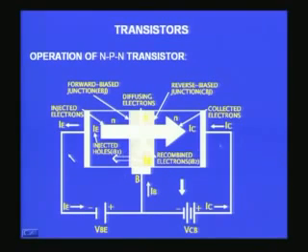So in the basic configuration, we can say there is a power supply between the emitter and base, called VBE here in this picture, and it is a very small voltage source, just about 1 or 2 volts. Whereas if you go to the collector base side, you find you have a much bigger power supply, and this is very important. So you require a larger voltage source on the collector base side, and a smaller voltage source on the base emitter junction, and they can be connected in different ways, as you can see.